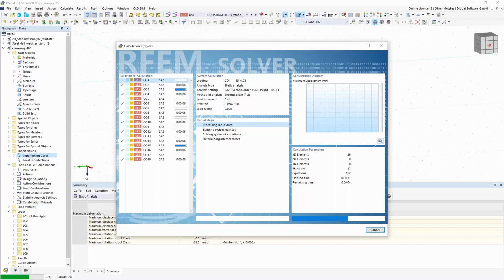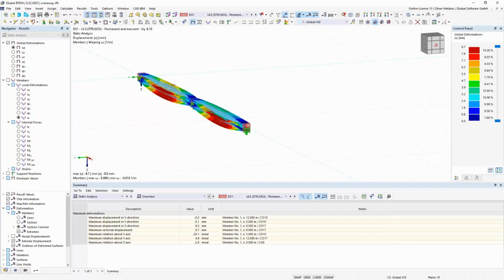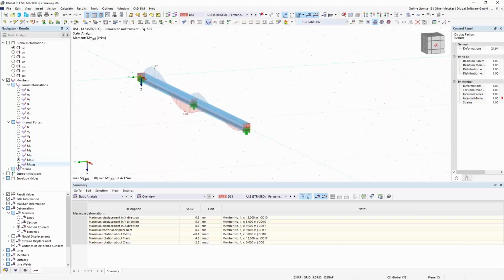So I could use these internal forces in a cross-section design check, and that will replace my stability design check for lateral torsional buckling. So that is possible according to Eurocode 3, and then I could use those internal forces. So all the internal forces I get now in this design situation number 1 can then be used also, for example, in stress-strain analysis add-on or also in the steel design add-on.